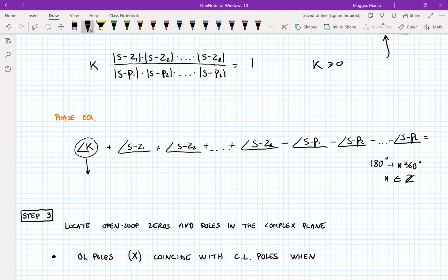and that is the phase associated with K. The phase associated with K is equal to 0. We can see it in a couple of ways. We can draw it on the S-plane, which is my favorite way of understanding. K is a positive number, so it's a positive real number. It's just a constant, so it lies on the positive real axis. So what is the angle that this complex number makes with the positive real axis? Well, that's just 0. So the phase is 0.